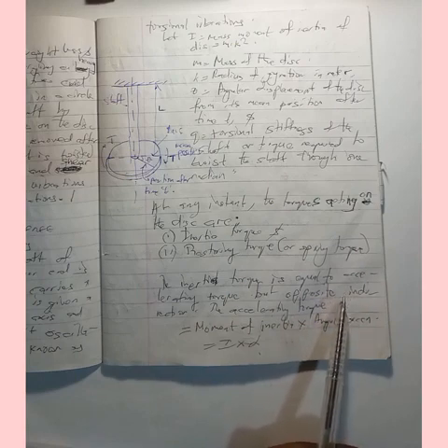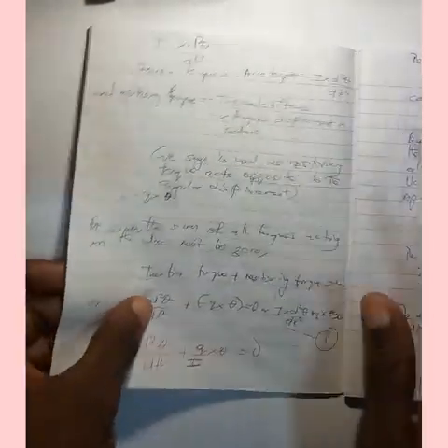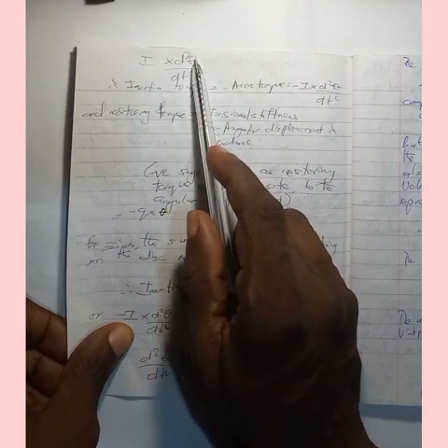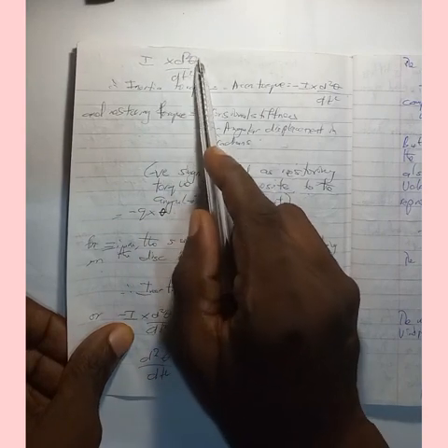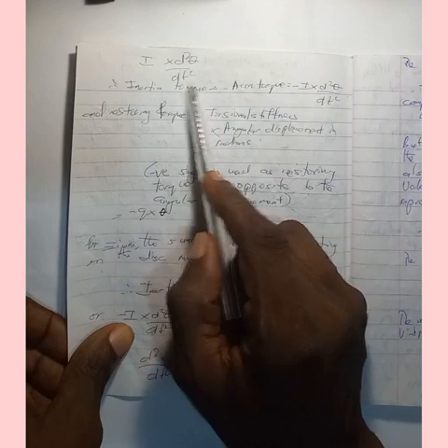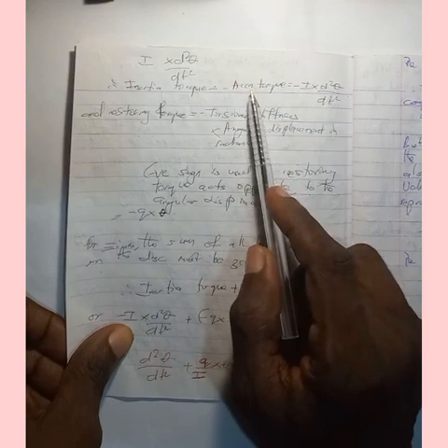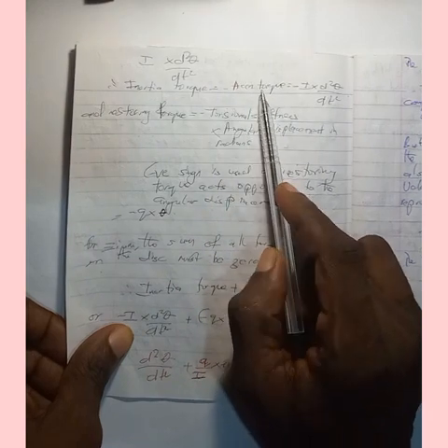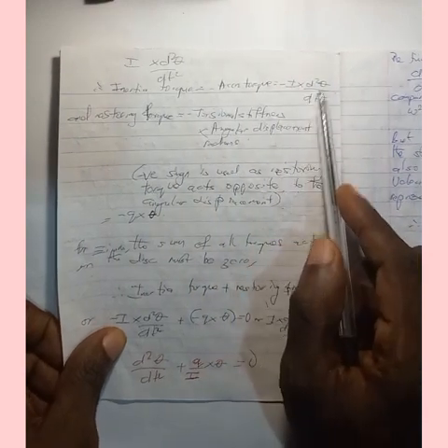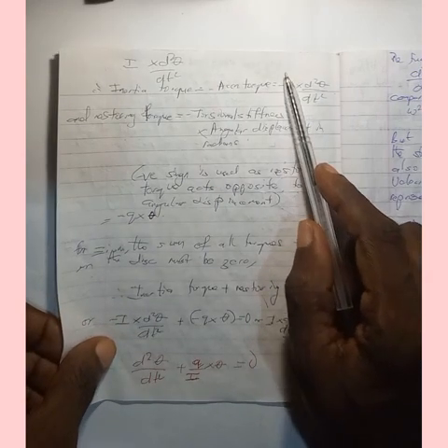This opposite in direction means that the torque is going to be negative, and that's what you can see here. We have I multiplied by d squared theta over dt squared. This d squared theta over dt squared is the same thing as alpha, and that's your angular acceleration. Therefore, we've established that the inertia torque is equal to the accelerating torque but in opposite direction. That means it's going to be minus I multiplied by d squared theta over dt squared. So that's it for inertia torque.